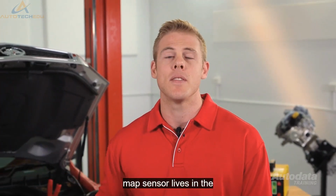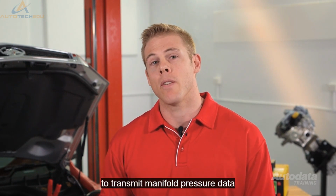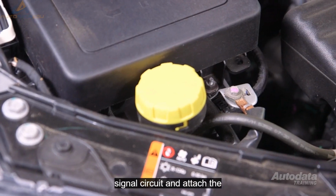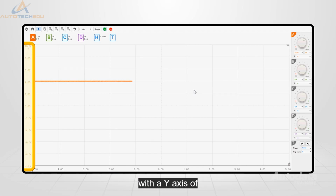The MAP sensor lives in the manifold or on the firewall. Its role is to transmit manifold pressure data to the ECM. To connect, back probe the sample lead at the signal circuit and attach the black to a known ground. Set up the scope with a Y-axis of 10 volts and a time base of 1 second.